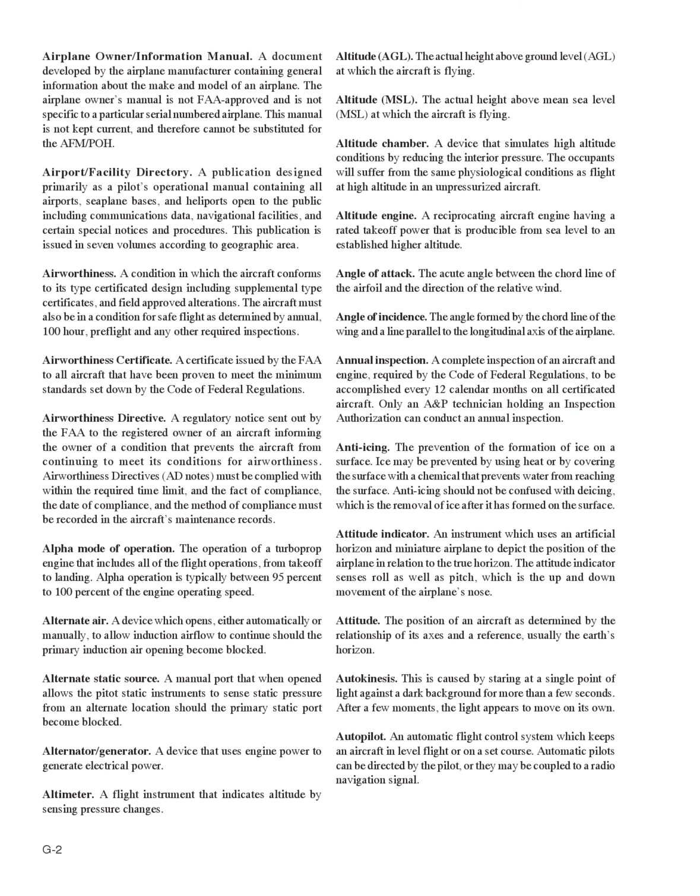Alpha mode of operation. The operation of a turboprop engine that includes all of the flight operations, from takeoff to landing. Alpha operation is typically between 95% to 100% of the engine operating speed.